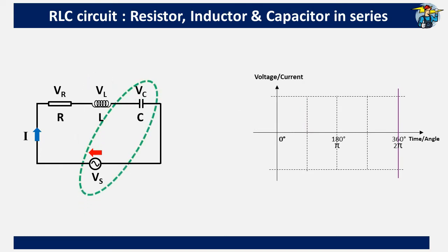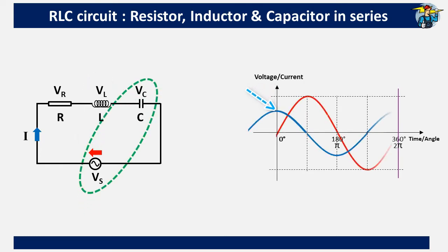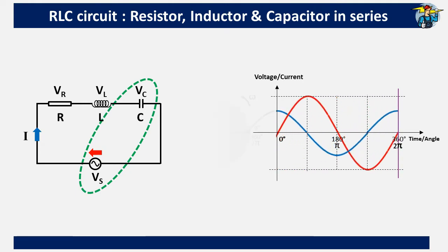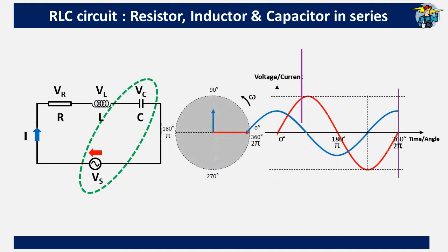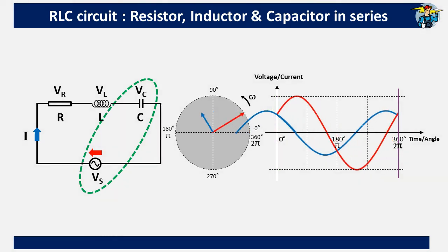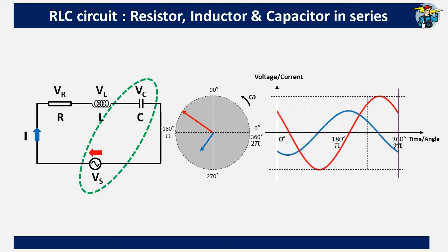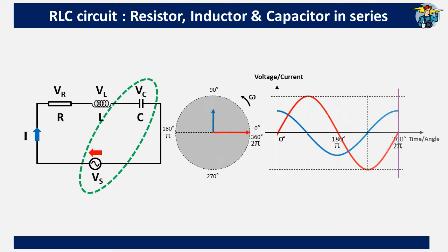Then on the capacitor, current wave has already started and gone to its maximum value, when voltage waveform is about to start from 0 value. This is clearer on the phasor diagram. Current waveform has started 90 degrees earlier from 0, and achieved its maximum value also, when voltage curve starts from 0. Current and voltage waveforms are out of phase by 90 degrees here also, but current is leading by 90 degrees in front of voltage.